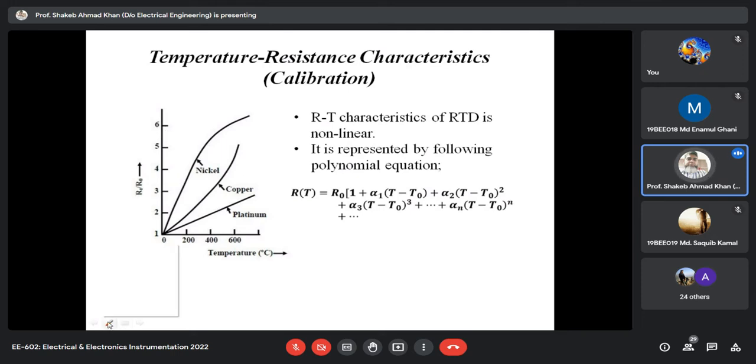A sensor basically converts the parameter which we want to measure into another suitable parameter which facilitates accurate measurement of the stimulus. Suppose this is X and it is converted into Y, and then we measure Y accurately. But our objective is not to measure Y but to measure X. Then how can we measure X by measuring Y?